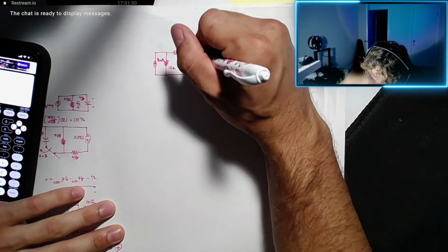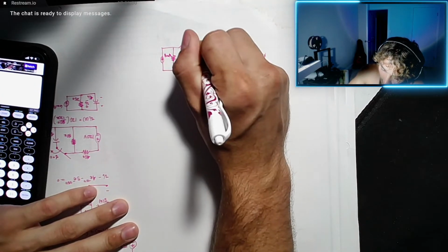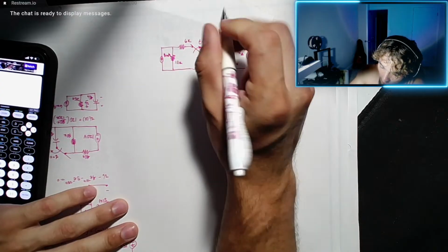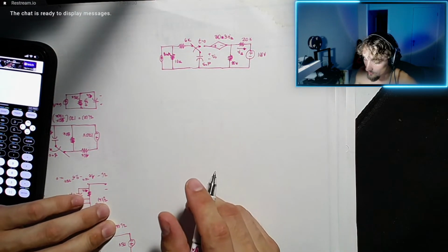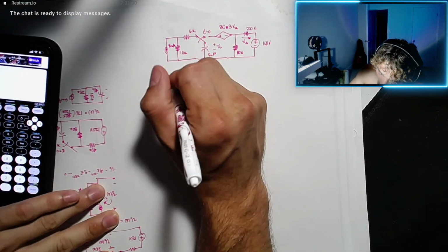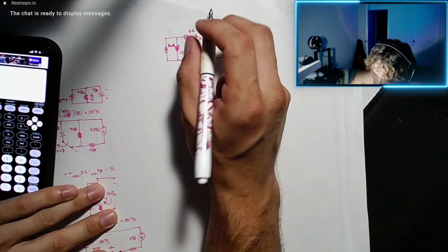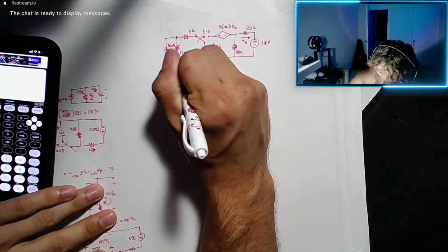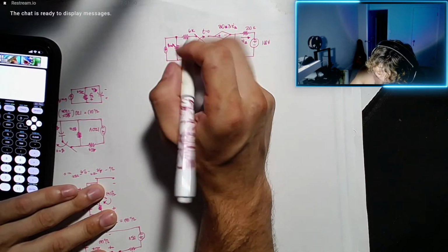Okay. Originally we're here, and at t equals 0, the switch flips to this side. Now we have a dependent source involved. Initially this capacitor is going to charge up through this current divider. So we have some current division going on here, so it's going to look like this.